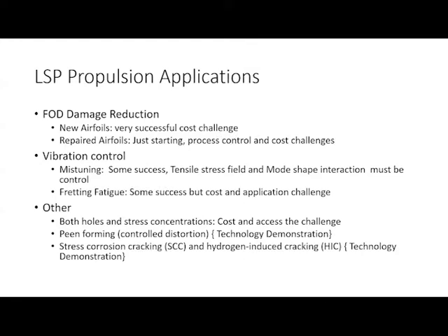So if you think about, I have an airfoil, it's LSP'd, I get a ding, and classically what you do with that airfoil, it comes to depot, and to reduce the stress concentration of that damaged area, you will do what we call blending. So you will take the stress concentration from nominally maybe an 8 or a 9 down to 1 to 2. Well, when you do that, you're machining.